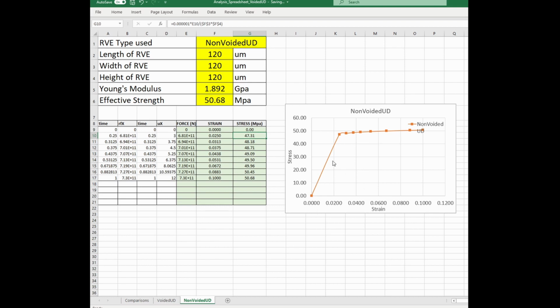What we need is the Young's modulus of this material. It's the slope of the linear elastic region, which is basically these first 2 points. Clearly this simulation jumped from 0 to this yield point rapidly, which is not ideal. So maybe you need to reduce the time step to allow for more gradual build up. But this is how the simulation came up, which is fine. It's not a problem. So we get that as our Young's modulus.